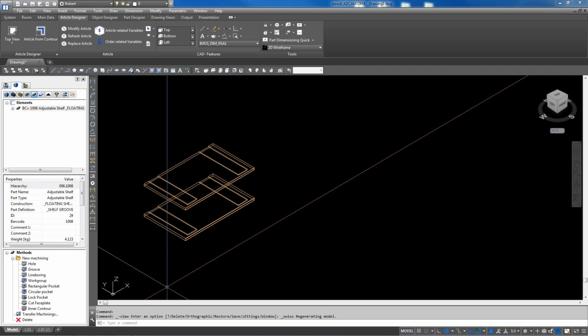I thought that instead of this, I would just bring in the same article two times, but done this way, it's actually probably easier to control and modify later on. If they decide to make the space between, let's say, 10 inches instead of 12, you just go to one article and modify the space. Or maybe they want 3 of those shelves, or who knows? Since it's an adjustable shelf, it goes divider drawer, so you can give it the overall weight you want and then locate it in the space with your linear division, however many you need.